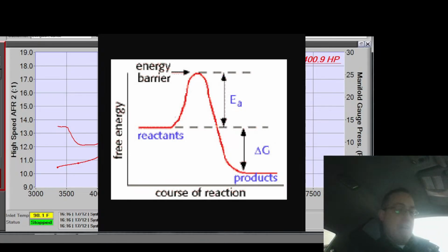But when you have so little reactants going in there and you're at a low engine speed and a low heat load, you need anything you can, and a low flow rate. That's another key too, right? When the airflow is slow in there, tumble is less, swirl is less, the mixture rate is just not there. So adding the EGR helps to preheat the stuff, but also increase the velocity. If I add a bunch of exhaust gas in there, that's non-combustible. That's not affecting my air-fuel ratio. It doesn't do anything to it.